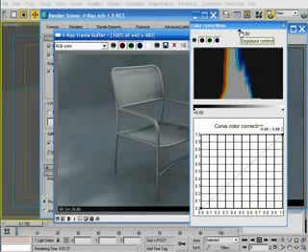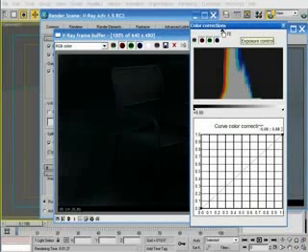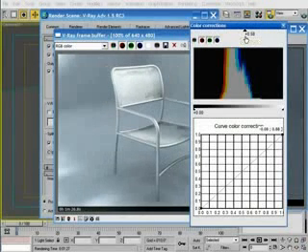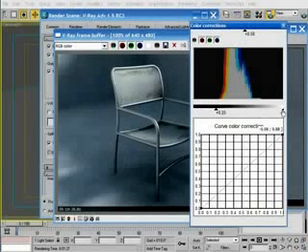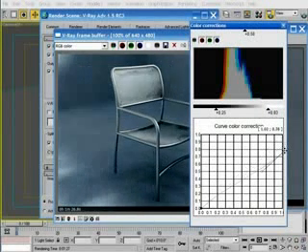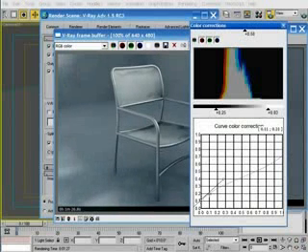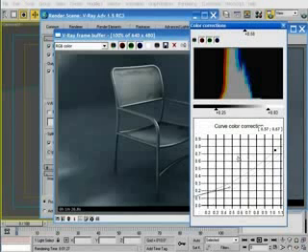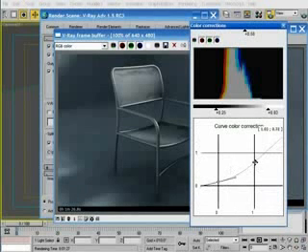The slider along the top of the Color Corrections window controls exposure. So as you can see, you can make slight adjustments to exposure to compensate for non-ideal lighting setup or for inadequate exposure adjustments made within the color mapping rollout. The sliders below the graph are the color levels corrections, which simply provide the min and max color level values for the image. The graph at the bottom is where color curve corrections are made. Here again, simple adjustments to compensate for the problems with the final rendered image can be made here. Also, you can use a wheel mouse to pan around and zoom in and out as you click and drag on the Bezier curve. Well, that's all I want to cover with the VRay frame buffer.